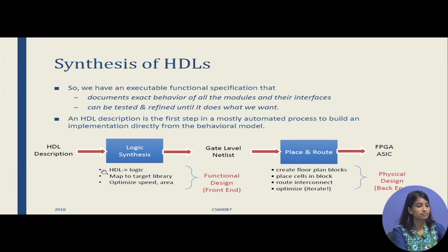The tool synthesizes a netlist. A netlist is generally a file in the EDIF format, which is electronic data interchange format. So that is technology independent. Any vendor can take a netlist and use it to do further processing of the system. I'll come to this later.